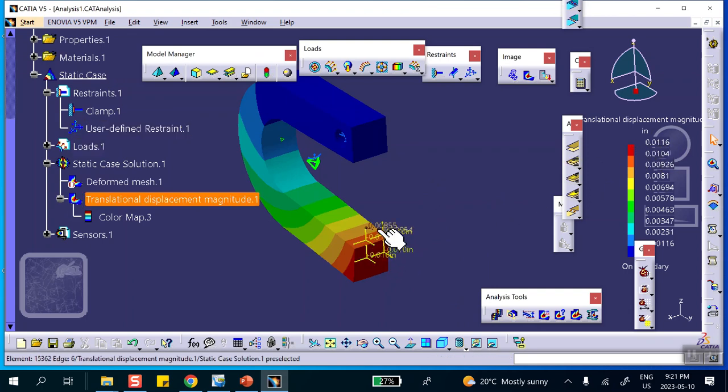That's because what I enforced is the downward displacement in the Z direction. But this also goes to the left, and it also shrinks sideways. This is the vector square root of downward displacement squared plus displacement x squared plus displacement y squared. That's why it's a little bit bigger than 0.01.